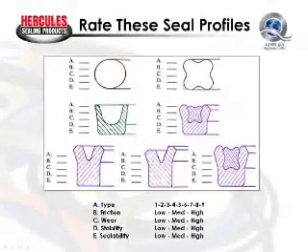Now the next profile we have would be that of a quad ring. Here we have a 4-lobed seal. Now instead of a round profile, we have a square profile. Okay, this is still fairly high up on the continuum, probably rated about an 8 because we do have a little free space around the outside edges here. But it's very high up on our squeeze list, friction is high, wear is high.